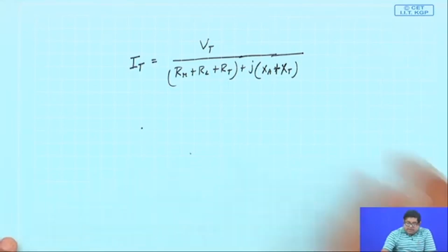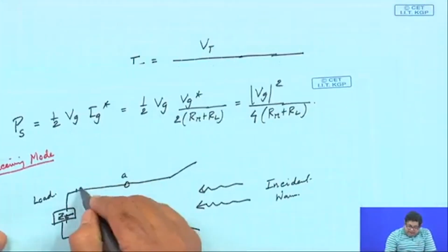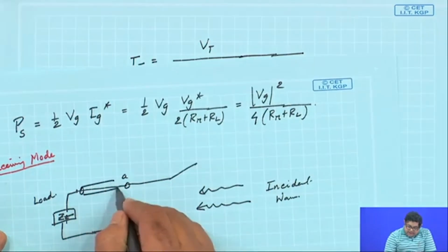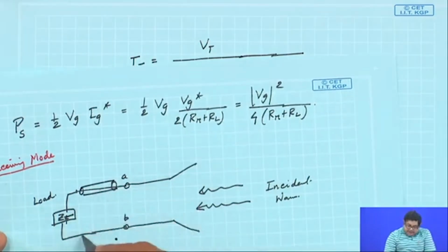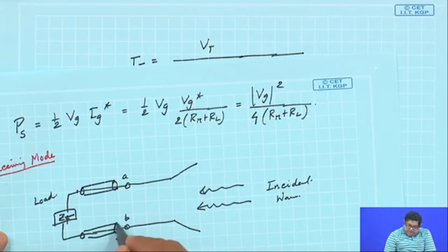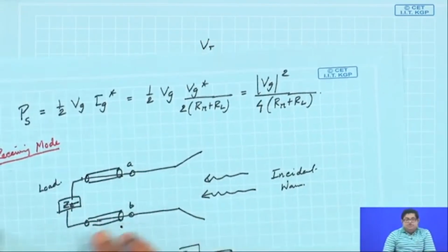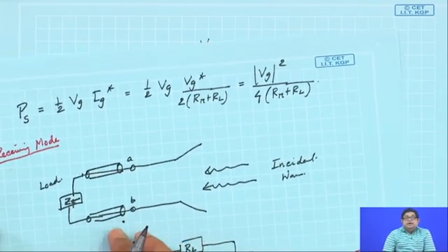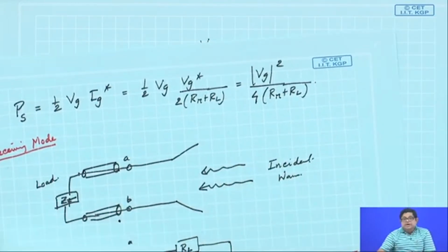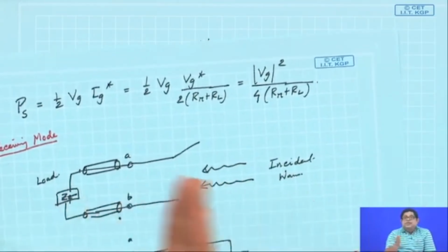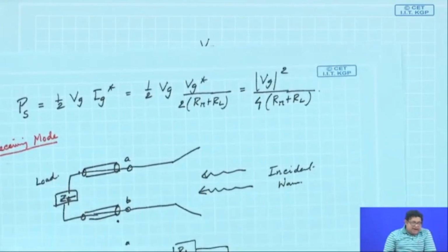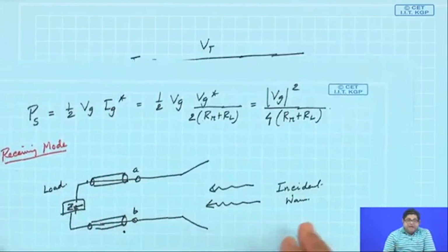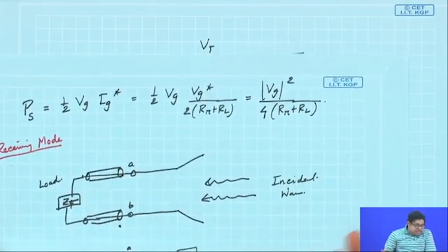Suppose there will be a transmission line here to connect it; that transmission line has a characteristic impedance. We are assuming it is matched, but characteristic impedance is a real quantity, and over a narrow frequency band only it will be matched. At other frequencies there will be a mismatch. So, that needs to be taken into account.